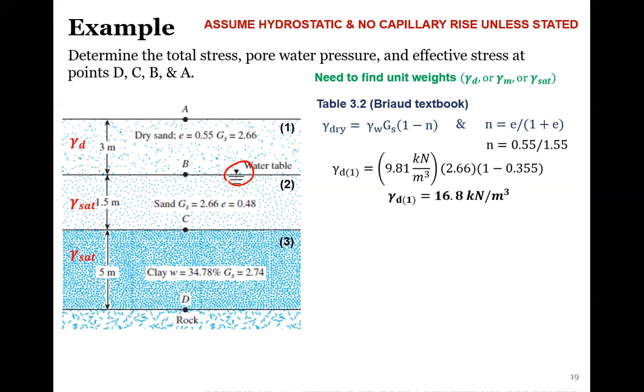If it's in pounds per cubic foot, it should always be somewhere between like 70 and 120, right? No, 150 is concrete. Having a soil that is more dense than concrete is really, really rare unless it's a rock. And water is 62.4. So it should always be more dense than water, less dense than concrete.